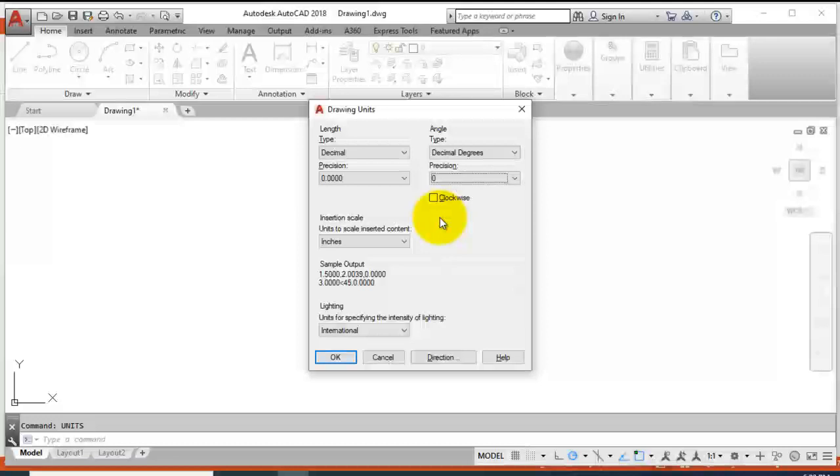That is, you go opposite to the direction of the clock. So in AutoCAD, if a line is at 12 o'clock, that is 90 degrees. The line is at angle 90 degrees. If a line is at 9 o'clock, that line is at angle 180 degrees.